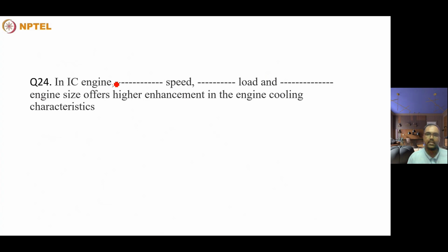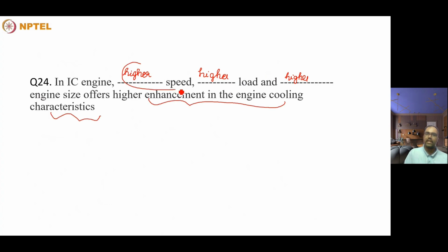This is based on the lecture. Higher the speed, higher the load, and higher the engine size enhances the engine cooling characteristics. Higher the speed introduces better turbulence and higher heat transfer coefficient. Because of that, heat transfer between the mixture as well as the surrounding cylinder increases.